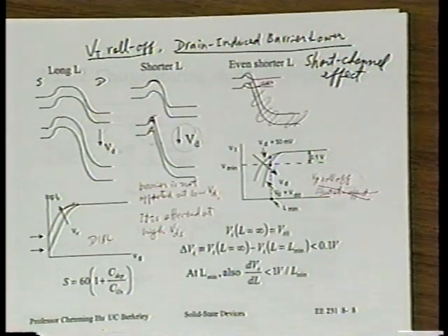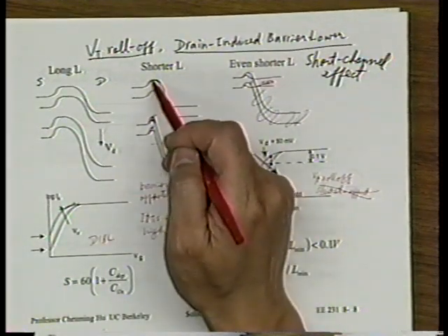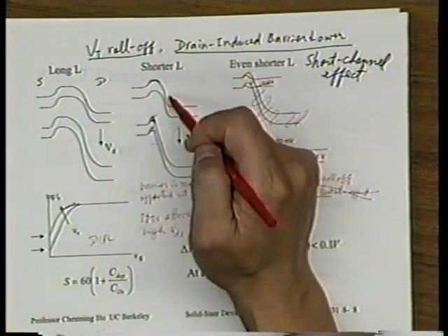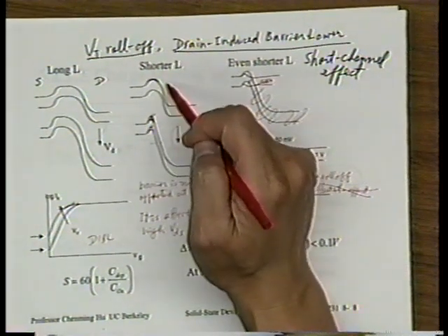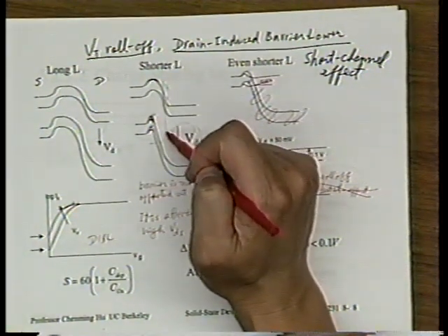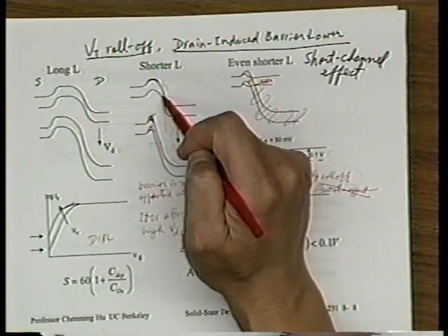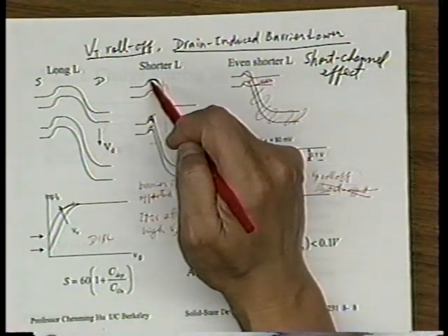And also in the subthreshold region, the minimum surface potential is not in fact at the point close to the drain, but a little bit apart from the drain. Is that true? Right, that's fine. That's why I emphasize this peak potential. I didn't say right at the drain. If you're looking at the metallurgical junction, it may be here. We don't care what it is at this point. We only look at the barrier height at the peak.